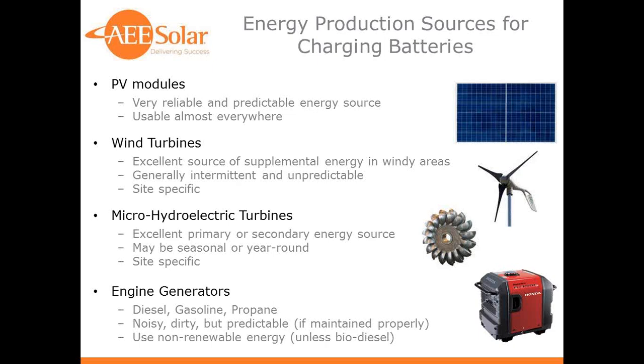And engine generators are used almost always as backup systems. Might be diesel or gasoline, although propane is really the most appropriate for off-grid houses, since most off-grid houses already have propane for things like cooking and water heating. They're noisy, but they're predictable. In a pinch, you can certainly get power out of them. Unless you use biodiesel, it's not a renewable source, however, and they're noisy and polluting.